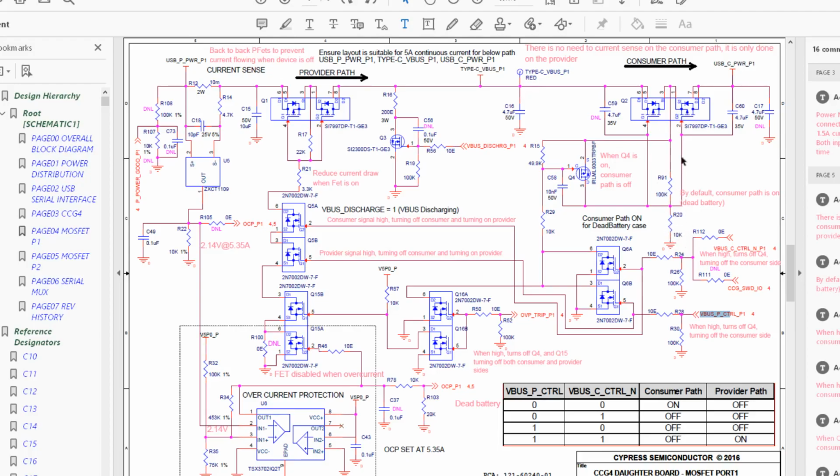When we pull the gate to ground, we get power here, and 20 volts here, and 20 volts on this pin. Now when we have 20 volts on this pin, 20 volts is pulled up to the gate. This is a PFET, so this turns off this gate. And it goes to here, we know both of these two are off, because these two are off.